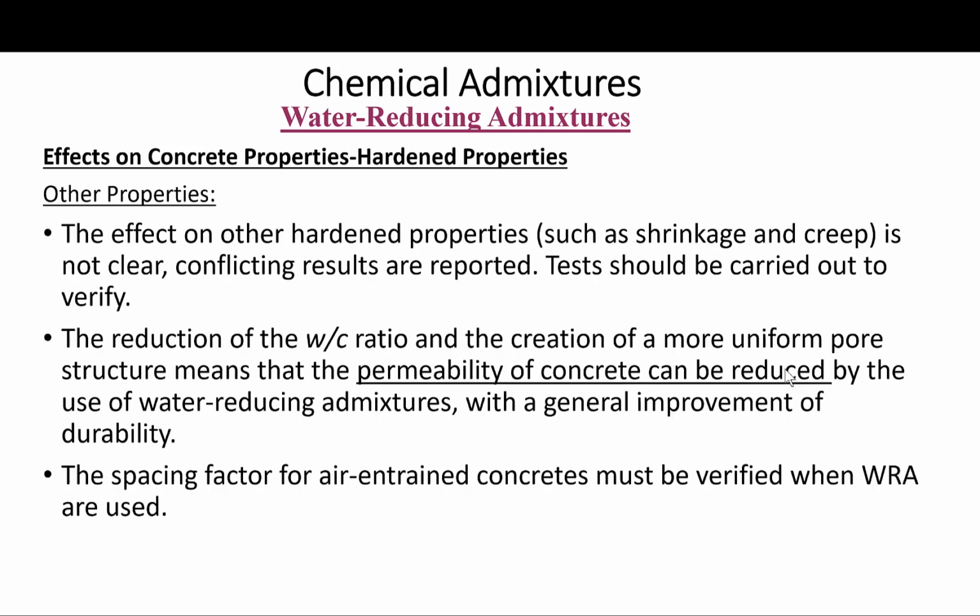Okay, so let's see the effect on other hardened properties of the concrete. It is often stated that water reducing admixtures increase the drying shrinkage and creep of concrete. However, the data are conflicting, as reported in the literature, and depend very much on the cement type and the particular admixture. And again, this really has to be related to the amount of the cement. As I said, reducing the amount of the cement and the water results in reduction.